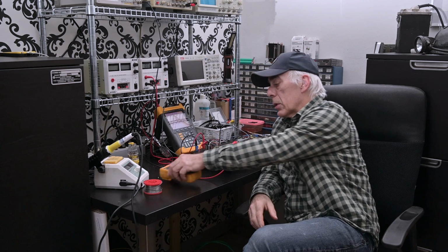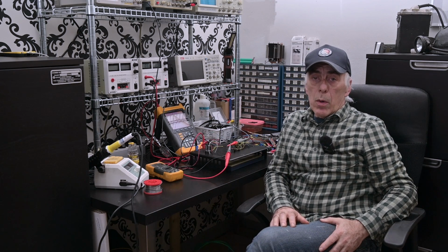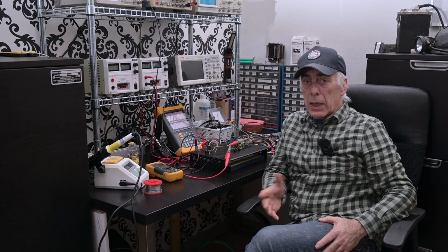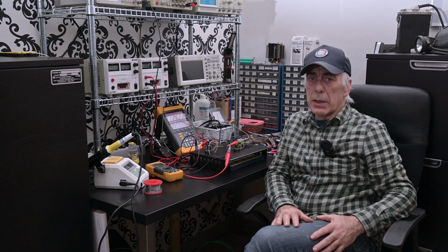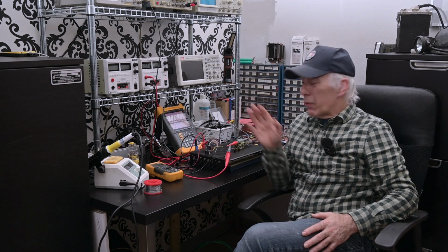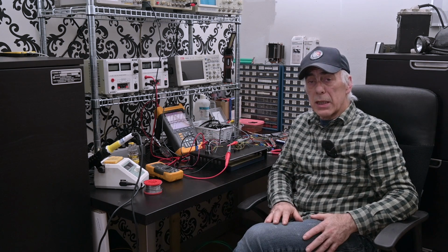Now when the CAN bus is in an idle state, it's going to show about 2.5 volts both on CAN high and CAN low. But you never know, that can change any moment in time. So it's very hard to check this out. So therefore, really, you should invest in an oscilloscope so you can actually see the traces.